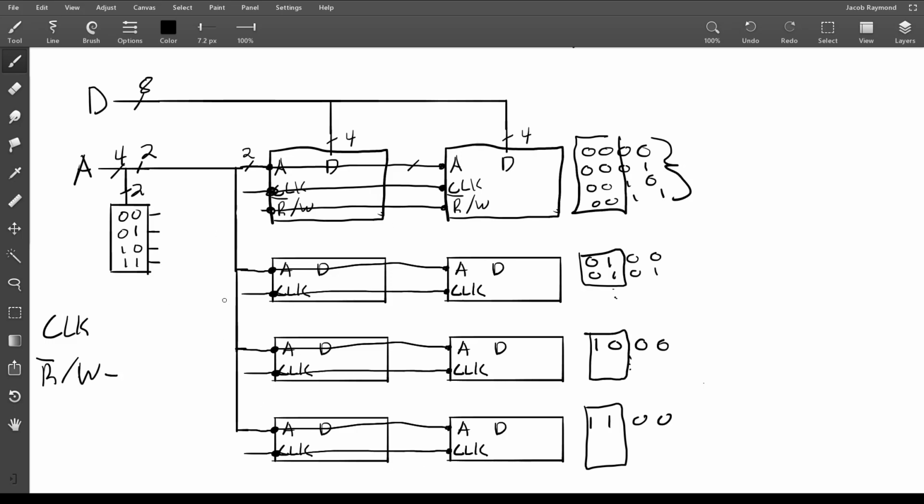It's just that wire gets connected to all of them. It would just create some extra hassle to do otherwise. And so we have our clock signal coming out of all these. And again, as with the last one, we'll place AND gates coming into all of these, with the clock signal being one of those inputs.